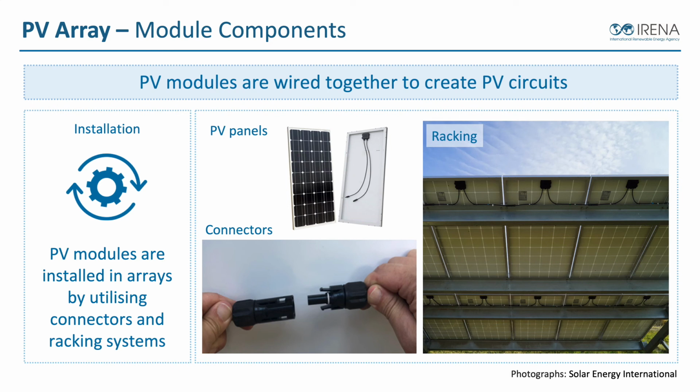The image we see here on the right is a ground mount structure, an elevated ground-mounted solar array. We can see the aluminum frames. We can see where it's bolted through to the steel structure. We can see the wiring connections and those connectors to make up the PV circuits. And that's how we build up PV arrays of larger size, by interconnecting the wiring and by mounting them to some sort of a structure. There are a few panels out there that don't have frames. We call them frameless modules. They have different clips that grab onto the glass, kind of like how we put windows in. But this is the majority of the common solar panels that we see out there in the market today.